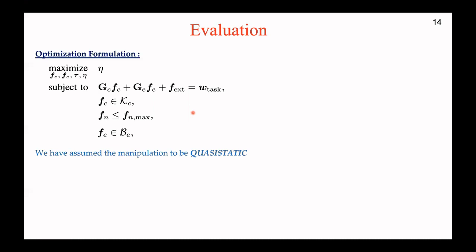The grasp metric computed using our SOCP-based formulation presented here is for a particular instant. However, we can use this formulation to compute a grasp metric during the whole task. This is because we can define a complex task as a sequence of constant screw motions about different screw axes.